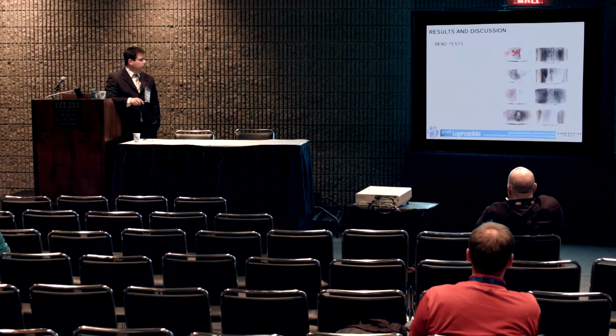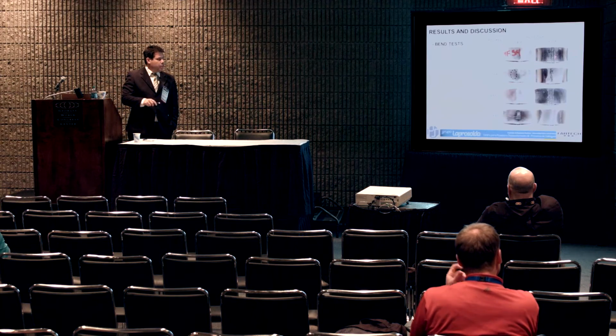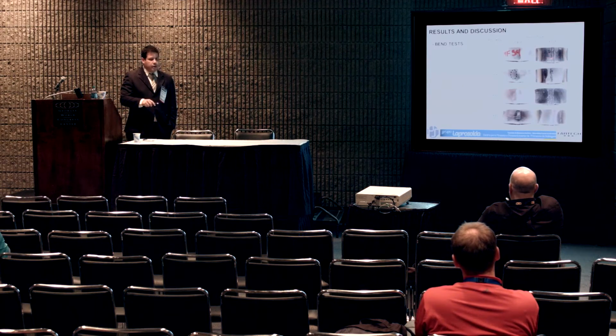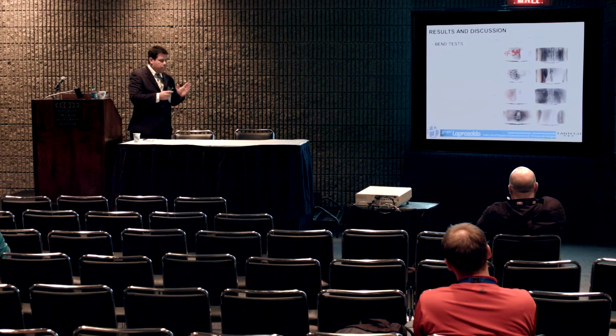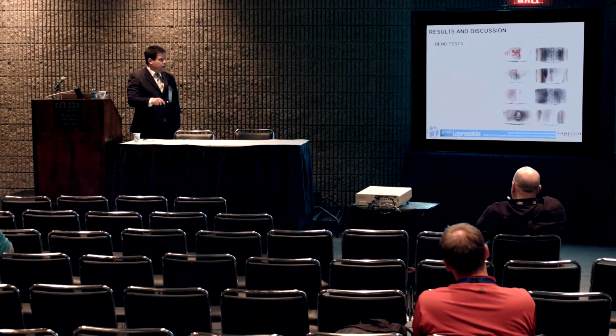But for the bend testing, yes, the problem with lack of fusion appears here. So you see a fracture here for the conventional gas metal arc welding. The other two, no. For STT in our previous test, yes. If you have that lack of fusion, you end up with problems in your bend testing.